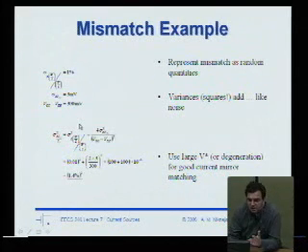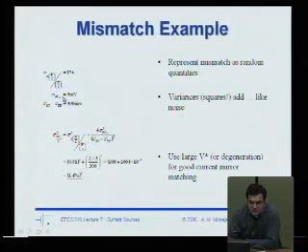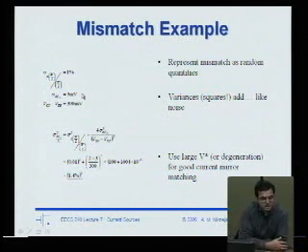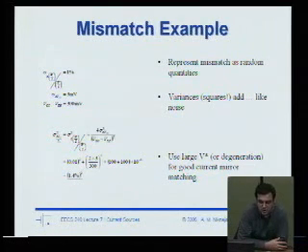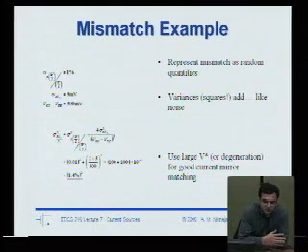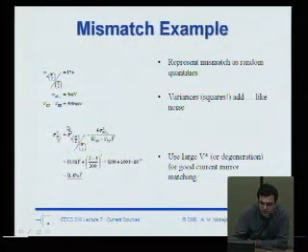And so here's a numerical example which gives you a little bit of insight. Let's say that the fab tells you that if you put two transistors nearby, the variance of the threshold voltage is about 3 millivolts. And let's say that you also know that your W over L variance is 1%.